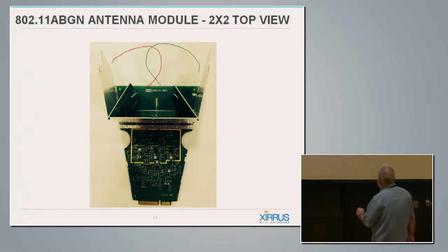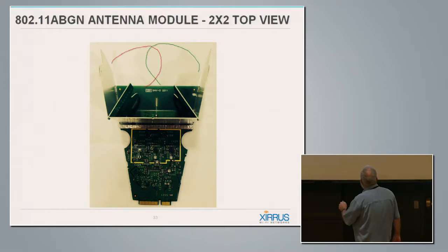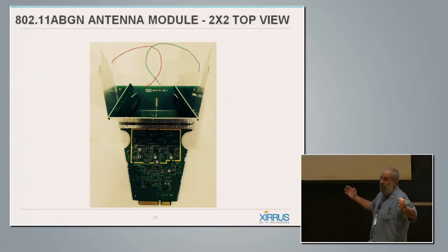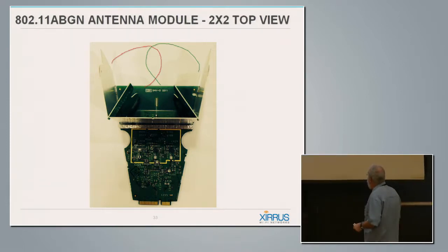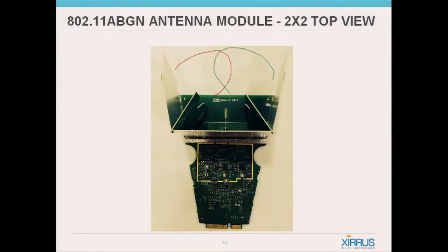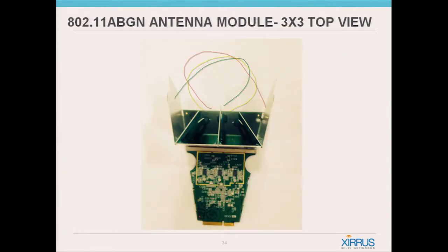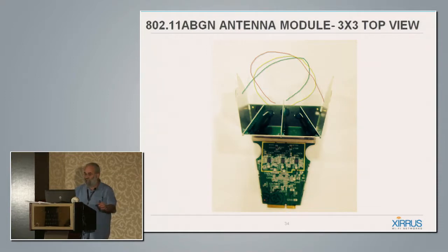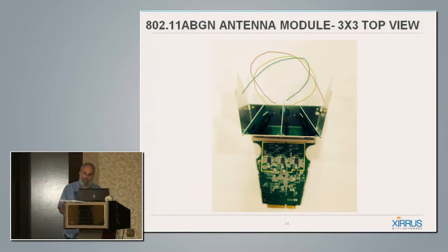So the overall look angles from that module is, you take those two beams together, you might get coverage of 120 degrees. So the illumination is quite efficient. The gain is very efficient. And in other applications, we can continue with the same idea and create a 3-channel design. So you have now 3 antennas. One looks at the center, the others to the side. So again, you get a very efficient illumination and gain in the 4 or 5 dB, which is kind of nice.